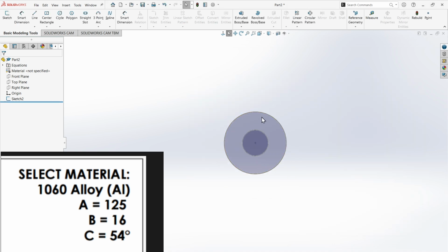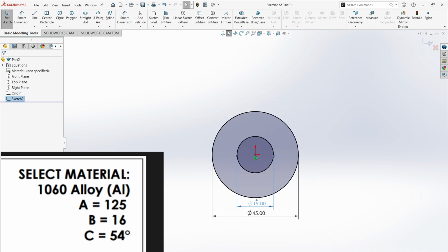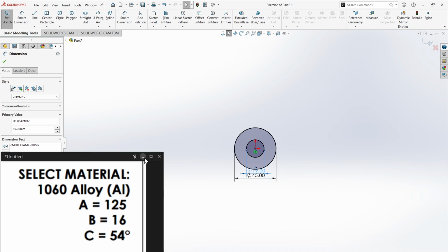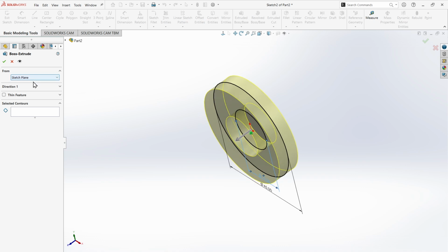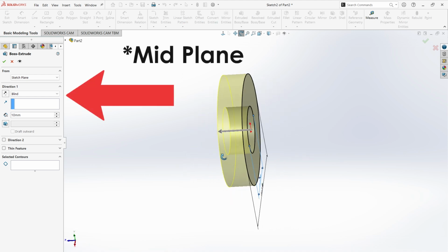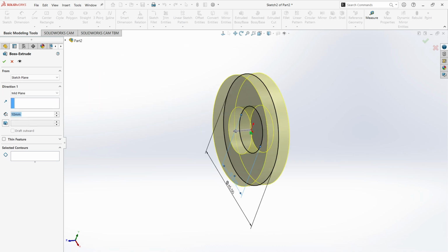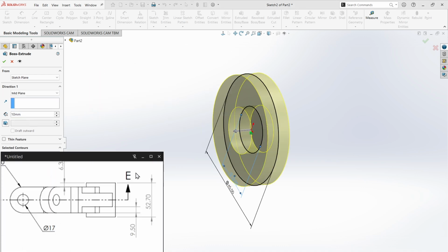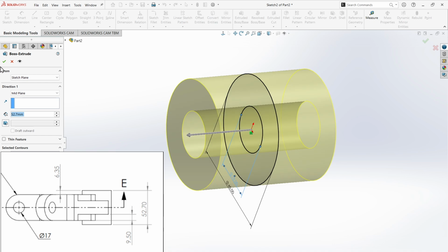So now let's get back into the sketch. So now that's sorted. Let's first extrude boss this. Let's pretend that we're going back to where everyone else will be. So we see here it's blind. We don't want it to be blind. We want it to be symmetrical on both sides. So do mid-plane extrusion. And we extrude by, see the circle from here to here, 52.7. That's correct.